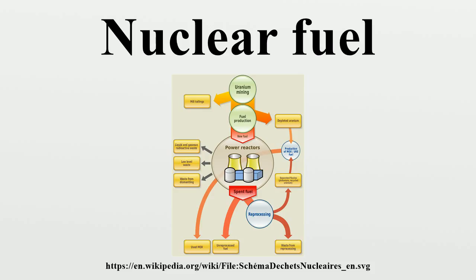The fuel is similar to PWR fuel except that the bundles are canned. That is, there is a thin tube surrounding each bundle. This is primarily done to prevent local density variations from affecting neutronics and thermal hydraulics of the reactor core.